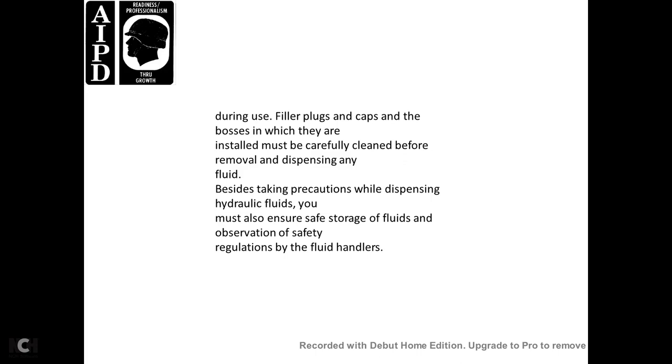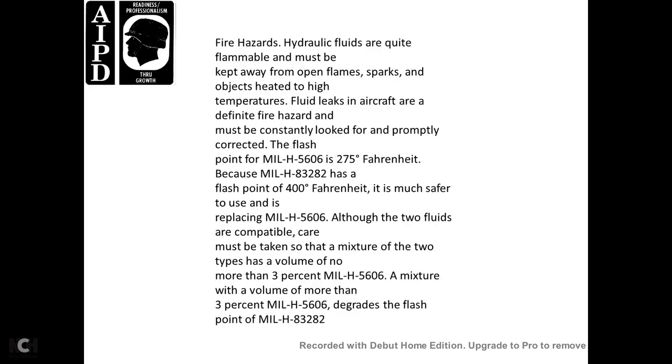Besides taking precautions when dispensing hydraulic fluids, it is most important to ensure the safety of storage of the fluids, observation of safety regulations, and fluid handlers. Fire hazards. Hydraulic fluids are quite flammable and must be kept away from open flames and sparks, objects with heat, and high temperatures. Fluid leaks from the aircraft that define a fire hazard must be looked at constantly and corrected promptly. The flash point of MIL-H-5606 is 275 degrees Fahrenheit.